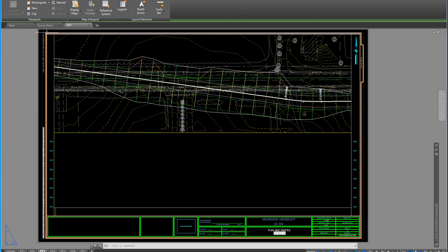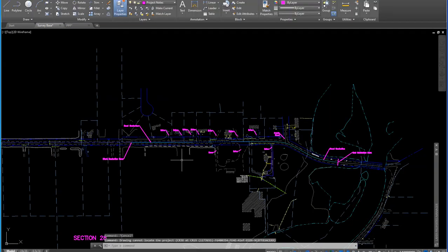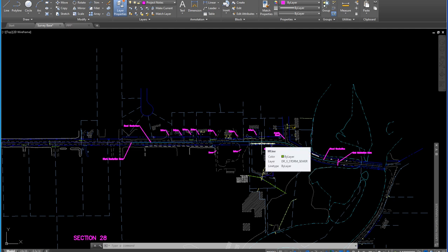Sorry, the yawning. You're going to make as many sheets as you need to cover from this call out, the start, until you come all the way down to the end call out down here. So maybe that's 4 sheets, maybe it's 5 sheets, whatever it takes. In each one, you're going to see a different portion. You may see this portion in the first one, then your second sheet picks up here and goes to there and stops. Your third sheet picks up here and goes to there in the viewport. So you're going to move that in a viewport. Viewports all need to be scaled 1/20 in each viewport as you go through. So each one of those sheets, you're going to make a PDF out of it.